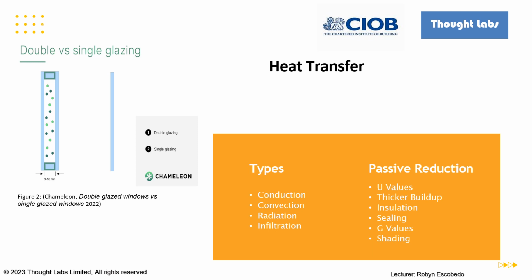A way for designers to reduce heat loss and hence reduce heating system demand would be to include a thermal break. This breaks the conduction cycle by including for something that isn't a solid within the construction build-up. For example, in a double glazed window, there is a gas break between the window panes. Conduction still occurs through the frame, but it is greatly reduced as it cannot pass through the gas. This heat loss and the demand on the heating system would be less than for a single glazed window.